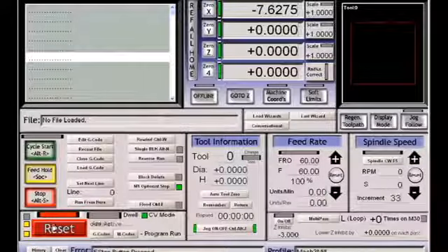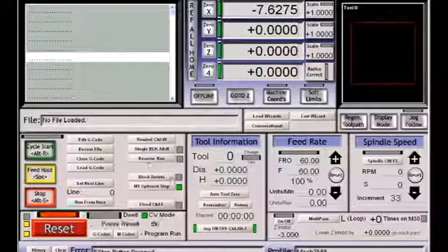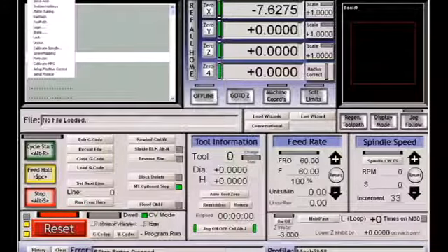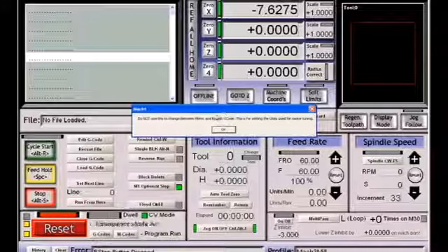like this screen with the reset button flashing, telling you that you have not reset the system. One of the first things that we're going to do is configure it. So we'll select the native units. You'll see you get a warning telling you not to use this selection to change between metric and English G-code.